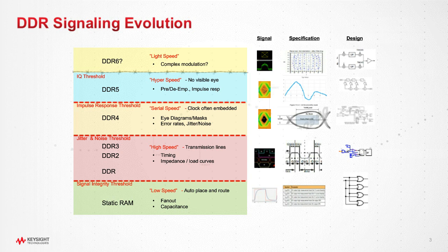In this realm, you don't think about things like timing, setup and hold times, like you did with high-speed digital. You still, of course, think about transmission lines, and you want to maintain that kind of signal integrity. But the way that you need to think about the signaling at the end is with the eye diagram itself and the concept called an eye mask, which is not one-dimensional like setup and hold, but it's two-dimensional because it deals with voltage and timing issues. And the big thing here that threw people for a loop in many cases was that it became a statistical spec.